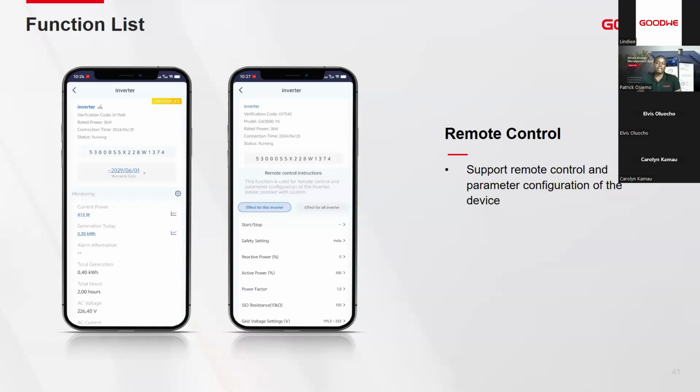Check the under frequency limits, over frequency limits. If it's within the inverter's operating, let me say, bandwidth, then that particular device can be adjusted to accommodate the fluctuations in either frequency or voltage.